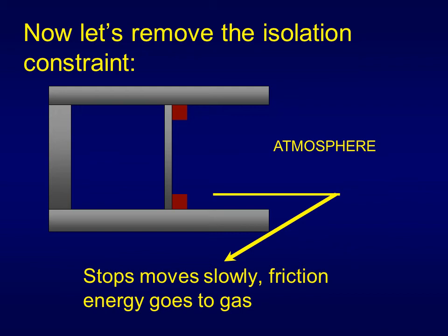So what happens? The work done by the gas is PdV of the gas. The work received by the atmosphere is PdV of the atmosphere. Now the pressure in the gas is higher than the pressure of the atmosphere, so there's some work lost in the transition. The atmosphere doesn't receive as much work as the piston does. You have to think about that a little bit, but that's what's happening.